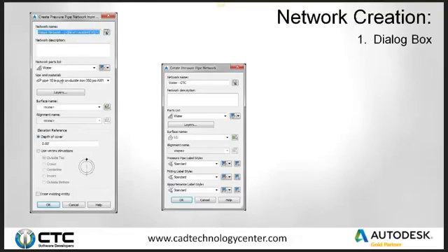It's going to say pick the size of material. So by default, all my pipe will be a 10-inch push-on ductile iron pipe rated at 350 psi. I can assign a layer, a surface in there, so it knows how I want to go about this, because right after there I have elevation reference, depth of cover.